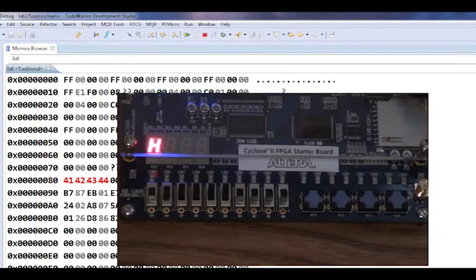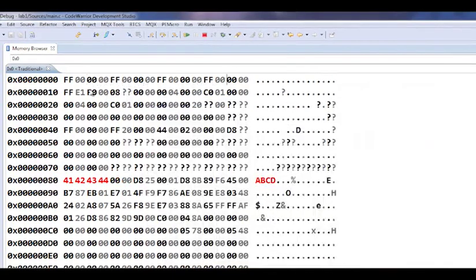And the help message that we're going to put up is going to be based on you being able to figure out what is the pattern for an E and putting it into address 2. And in address 5, we're going to put the 2-digit hex number that makes an L and a P here, and that's one of the first initials in your lab that you're going to have. By putting something into address 1, 2, 3, 4, 5, and 6, we can change our 4 7-segment displays.